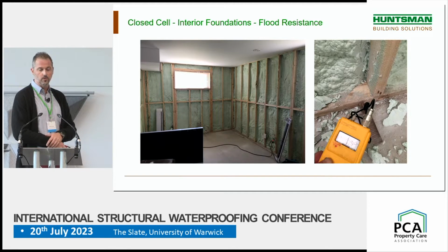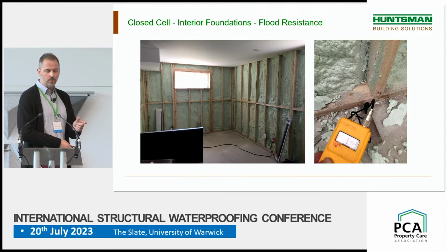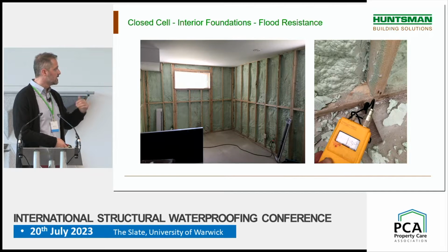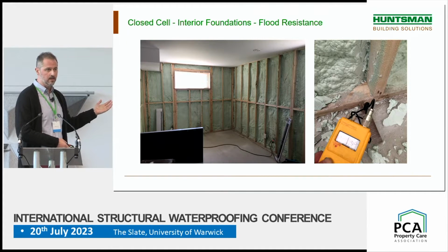We also measured the wood structure for humidity content, and the only portion of the wood that still had a higher humidity content, at 30%, was the portion that was embedded in the foam. So all that it needed is additional ventilation and dehumidification for a couple days. Then all that needed to be removed was the interior finish, and they replaced it. So the insulation and the structure were maintained following the major flood. With other types of insulation, probably it would have to be removed.